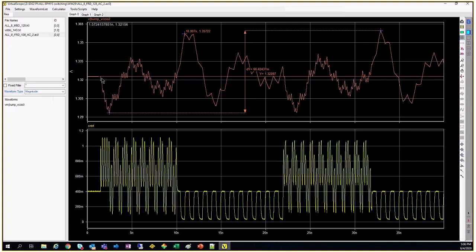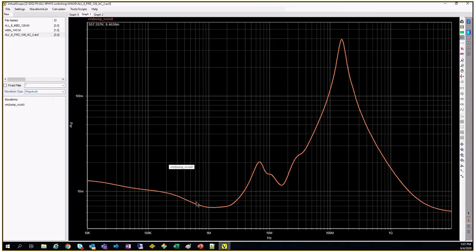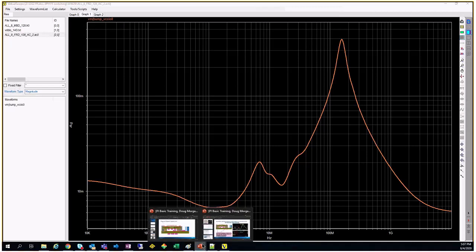Okay. So that's where if you put a cap, we say cap reduces noise, meaning basically the impedance comes down, right? When you add a cap, the impedance can come down. So you're seeing your package inductance and board inductance going up, and your package caps are playing a role. So if you see here, this is the best diagram to explain.